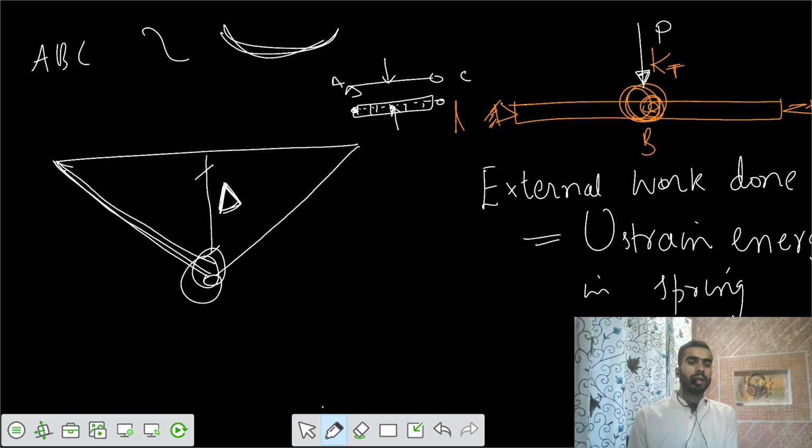But your spring is there, that means rotation of that member would be allowed. So I would say there is some theta developed, and theta is constant for this length. There is also some theta developed on the other side because your length is the same. You can take this length L, so your L is same. That means theta developed is also same. And there is some 2 theta that is contributed by that spring of stiffness KT.